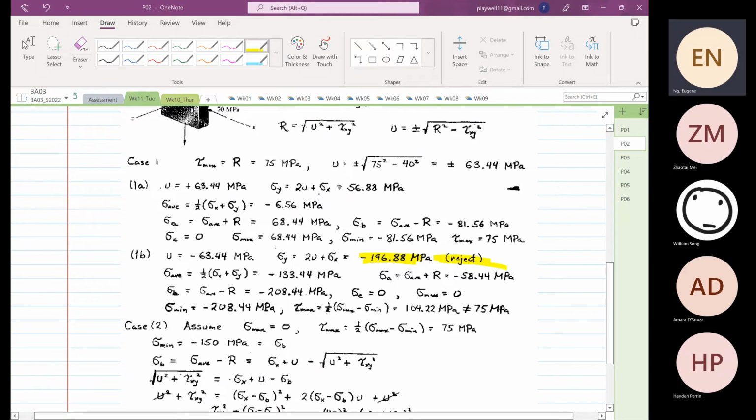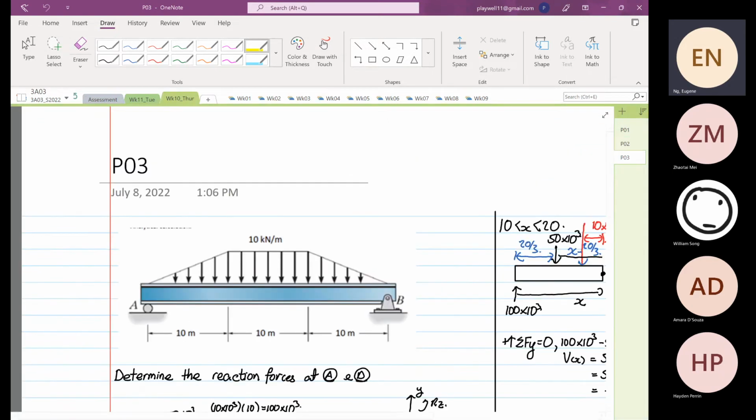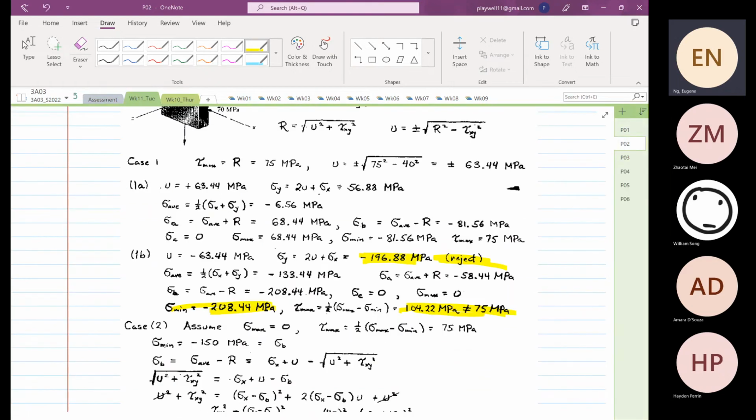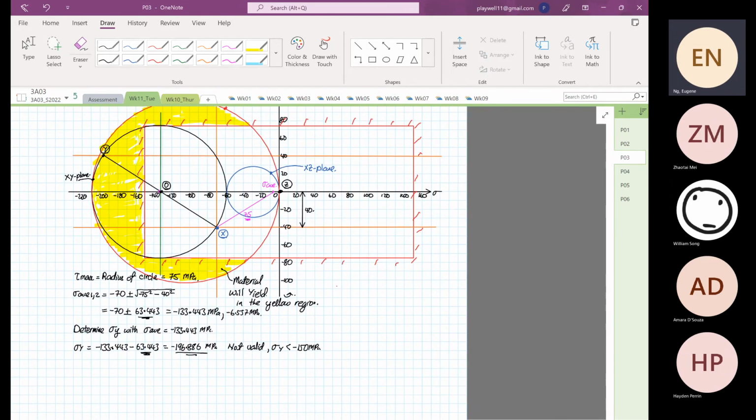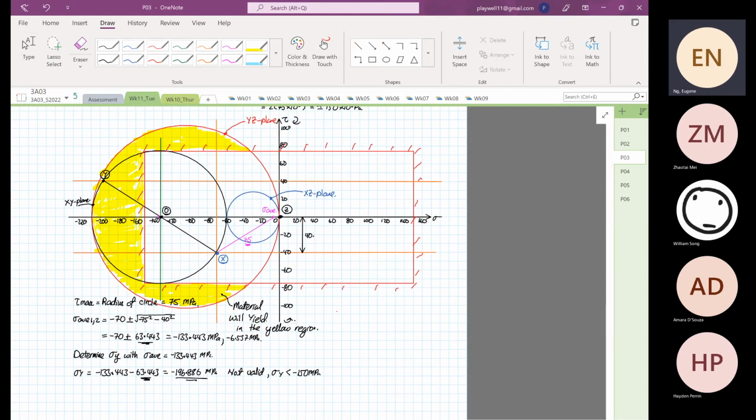They calculate the min and the max, same as what we've done, but over here, without forming those equations, just by looking at the math that we use, it's so simple, yes or no? You don't need to form any equation. Just construct the Mohr circle, construct the box, construct the Mohr circle. You know that this is not the valid answer and why it is not valid.